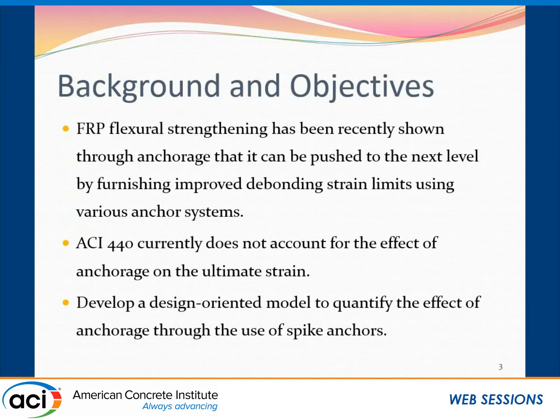FRP flexural strengthening has become very popular. A lot of research has been conducted in that area. However, in order to push it to the next stage, as we all know, we are limited in ACI 440 by the debonding strain limit, and ACI 440 currently does not account for anchorage. In order to push the FRP behavior to the next stage, we would need to exceed that limit, and that could be done using anchorage systems.